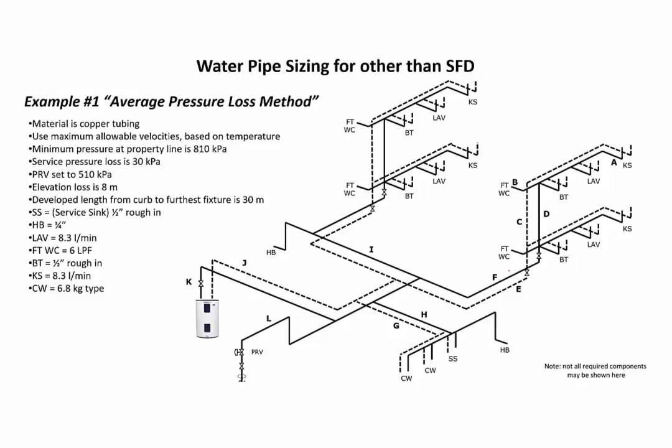Okay, just looking at all our loading here one more time. I'd like to point out that these 4 suites are typical here. These would be private loads for those fixtures in those suites. And then we have some sort of communal space down here. We've got some hose bibs, we'll call them public hose bibs. There's a service sink and 2 clothes washers down in a laundry room. So that's for use by all the occupants. We'll go with public loads for these fixtures, private loads for the suites.